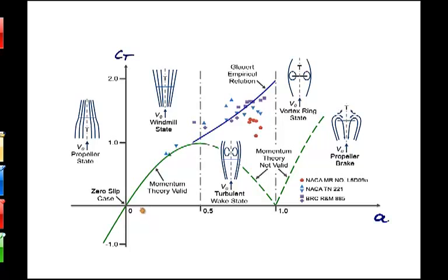What we know so far is, well, we know the parabola. We recognize the parabola for the thrust coefficient, which is the green line here. And yes, the green line turns from solid into a dashed line for axial induction factors A larger than 1/2, because we saw that in this case the exit velocity at the end of the stream tube reverses, and so because of that momentum theory is no longer valid.